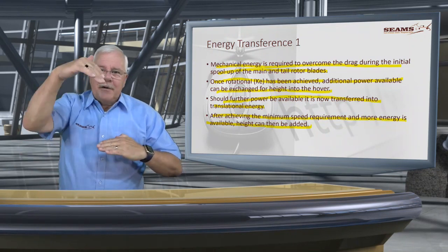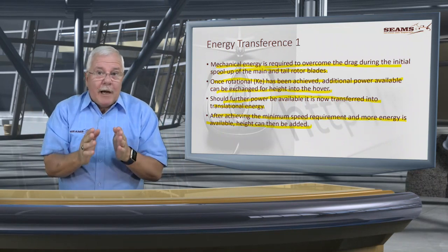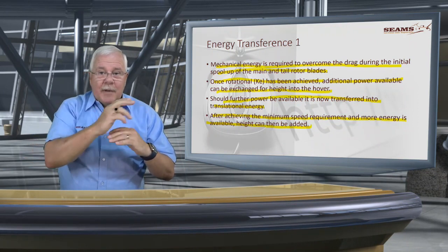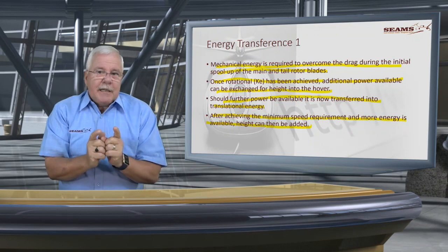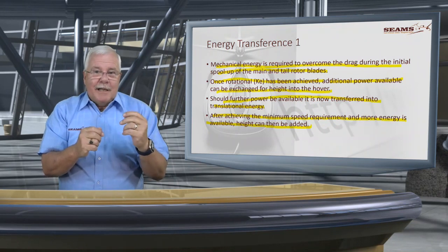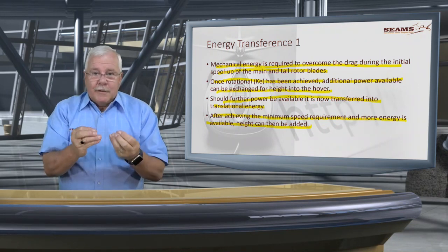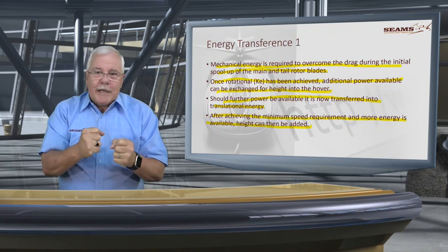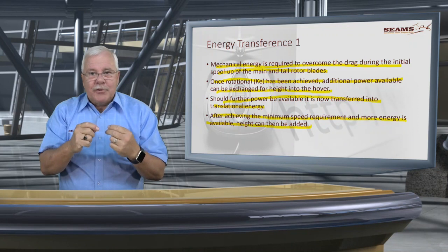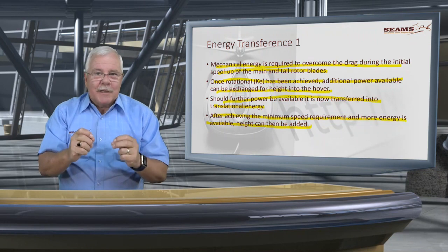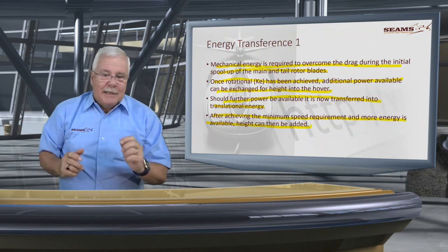Oh yes, we can go directly in and do other funny stuff, but remember, we're now with the basics. In other words, spool up, forward, and then climb. And each section needs extra energy. So height, as you're attaining it, is actually your vault. Not for money, but for kinetic energy. Because that is where you store the energy, because height has got the potential to turn into kinetic energy or speed. And that is why height becomes such a valuable item in the bag.